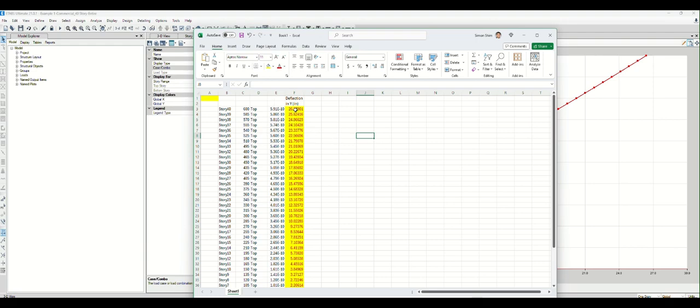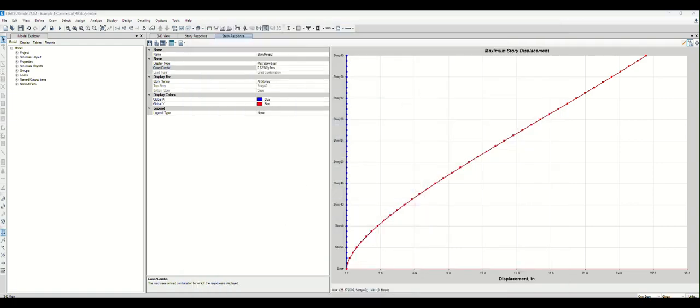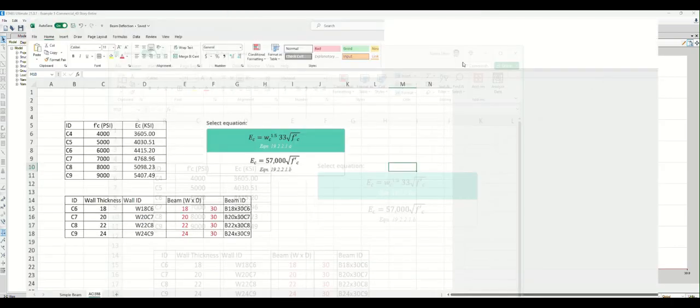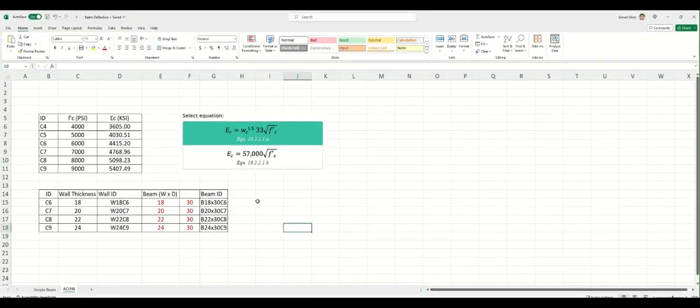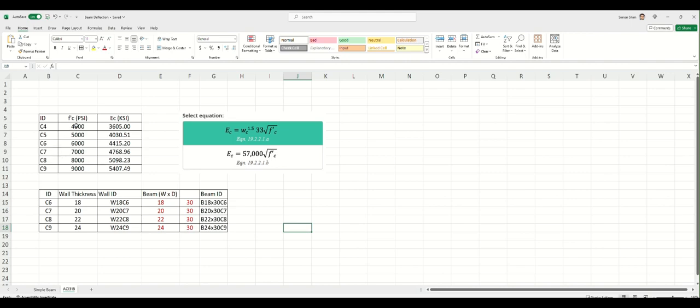Whatever your default wall thickness, if you're using 12-inch thickness, you maybe end up with a pretty significant deflection in one weak axis, right? So what we're gonna do now is basically increase the lateral stiffness, which is about moment of inertia and Young's modulus. Here I create the table, right? We maybe create more material properties based upon the concrete strength.